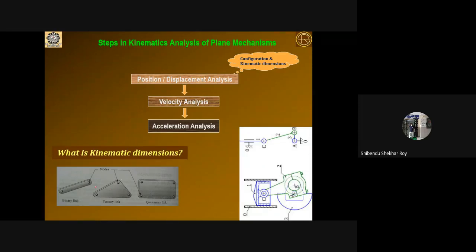Now see the dimension which is important from the kinematic analysis point of view. Let us say this one, is it important? How much is the width here? Because my objective is to build the relationship between how much sliding motion, or how much displacement, I want at the slider side, so that we will get the RPM at the crank end, and ultimately, through transmission, you will get the wheel speed in an IC engine.